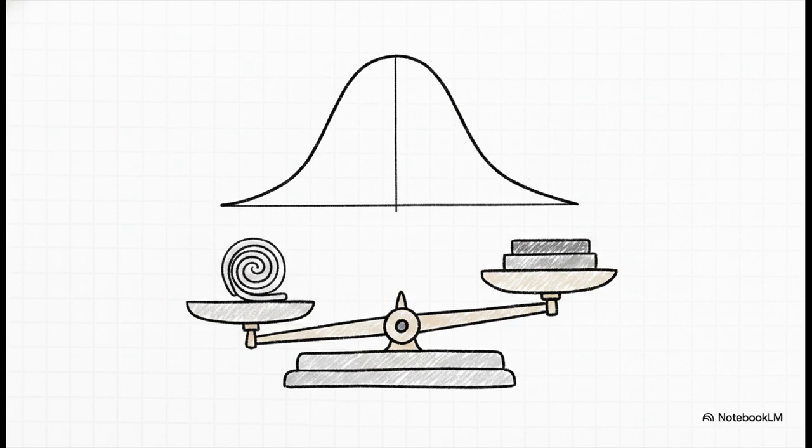Here's the twist. Peak efficiency in a transformer actually does not occur at full load. Maximum efficiency hits at the exact mathematical point where your variable copper losses equal your constant core losses. For instance, if you have a unit with 1 kilowatt of core loss and 4 kilowatts of copper loss at full load, its efficiency curve actually peaks right around half load, not full load.